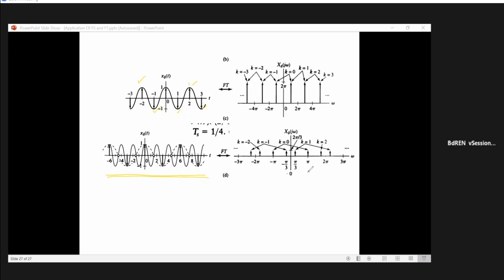But if we further decrease the sampling rate, your sampling can be something like this. The sampling appears here, the blank dots. Then you can easily see that this dotted curve and this solid curve was our original signal, but using the samples, for example, your open circles, you can also draw a sinusoidal signal, something like this.